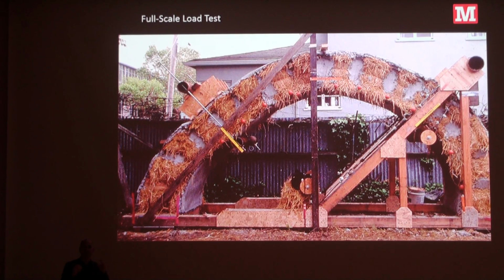And we took this building and we subjected it to about 130% of its weight sideways. So it'd be like taking it, turning it on its side and shaking it a little bit. And then after that was done, we had a whole bunch of people pile up on the roof to do the gravity test. So back to that point about not needing precision or accuracy to make a decision, all I needed was confidence that I could build this. And so, it's kind of hokey and it's country granola, but I think it's good sound engineering.